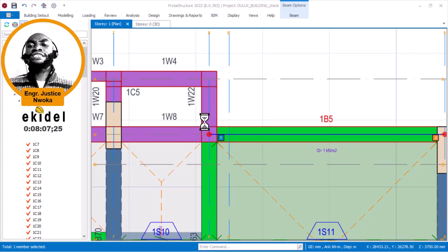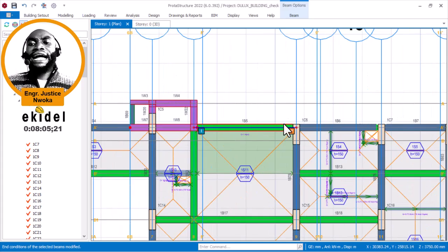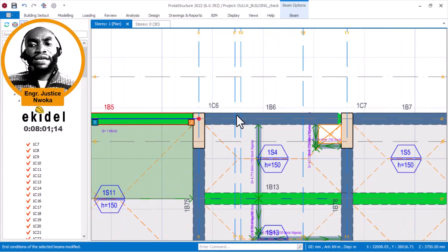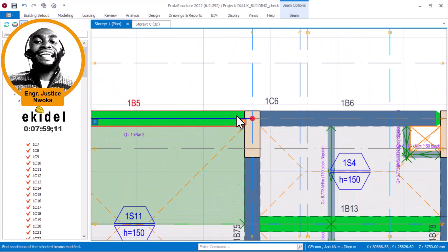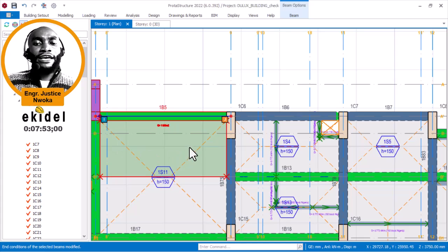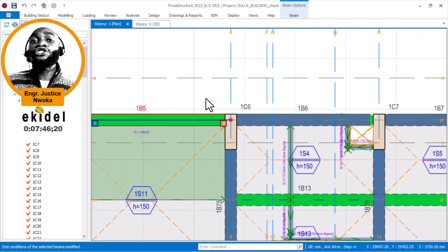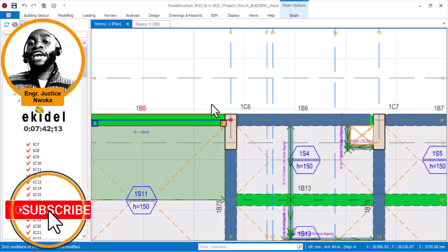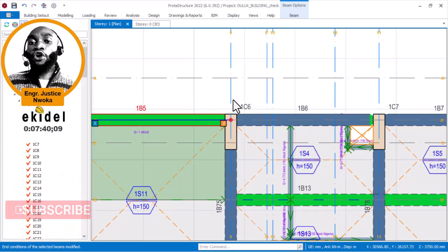So with this, you can see how I am applying this, knowing that this is a column, and after this column there's a beam and there's a beam, so this place cannot be an end of this beam 5, because this now becomes a continuous beam. Because if I draw the moment diagram right now, you can see that here it will hog like this. Because of this hogging, it has induced a top moment, which requires a high top reinforcement on this side. Okay, and all that. That's fine.